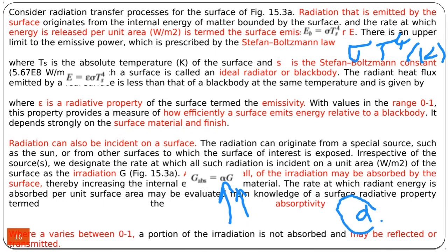This is why we have very high temperatures on the asphalts during the summertime, right? Because it's black. Black absorbs the maximum radiation. And if you measure the temperature of asphalt, it could be close to 100 degrees, whereas the temperature outside is only 30 degrees. It has nothing to do with the air temperature. It's because of the radiation absorbed by this black surface.